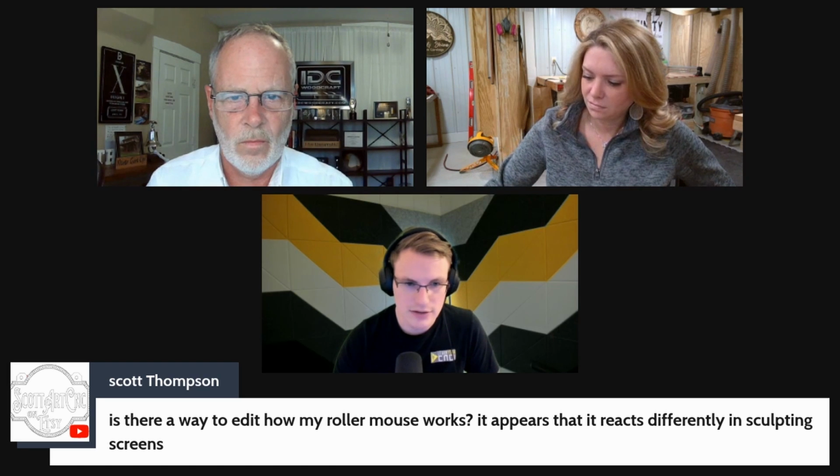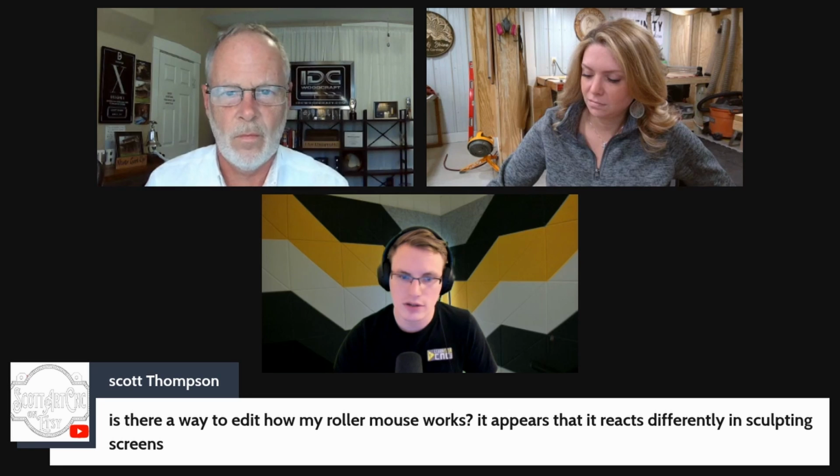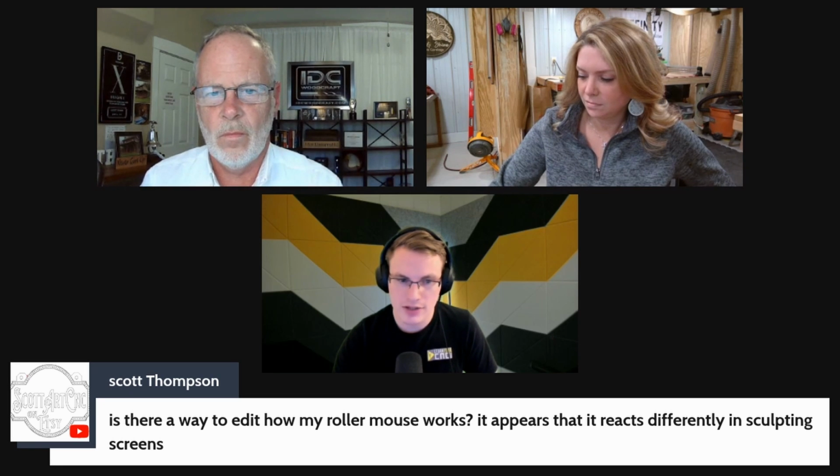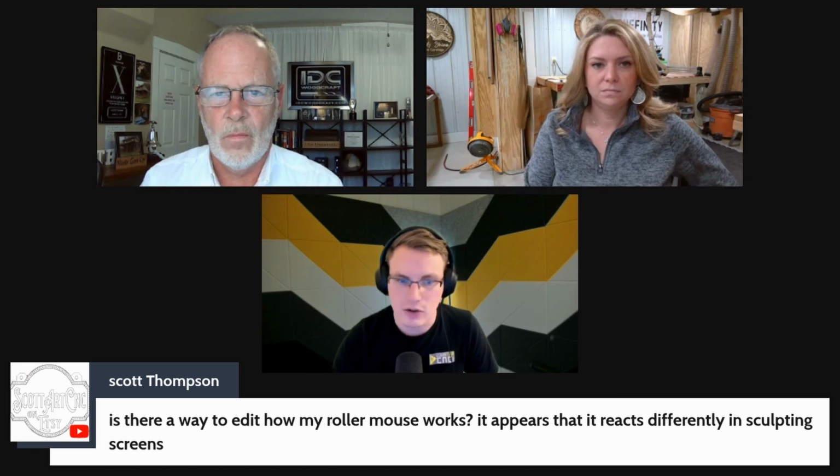That's a point too, just to mention, Kyle, about the switching of the left mouse button to the right mouse button. In the 3D view, they did change a little bit on how the controls are, especially with the left mouse button and right mouse button. It did take me a little bit to get used to that. You can set it back to the old controls in the edit options, but you will lose some of the new features if you do that. So if you really don't like the new way, you could switch it back. And in the edit, you go to options. There'll be a modern option, and there'll be a legacy option. If you set it back to legacy, that will switch it back to the old way.